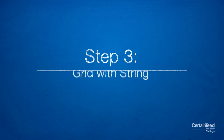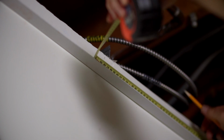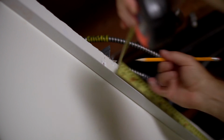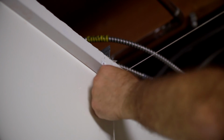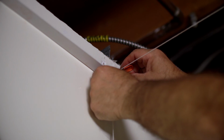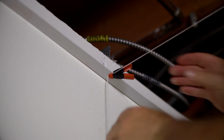Step 3. Laying out your grid with string. This process will make the installation and placement of the grid much easier. To locate the placement of the main tees, stretch a string across the room at ceiling height. Use the hanger wire as your guide. Use a clip or small clamp to secure the strings firmly to the bottom of the wall angle.